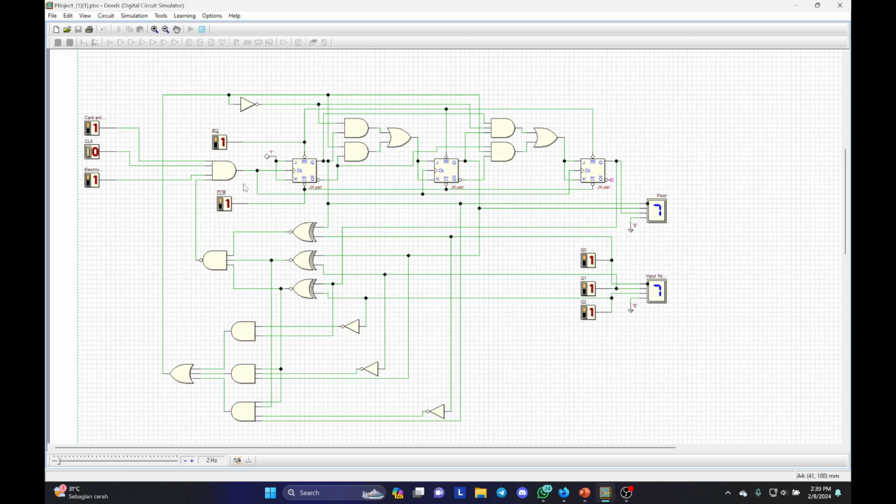Okay, for the last example, maybe let's go to the ground floor, from the seventh floor to the ground floor. Okay, because section A is greater than section B, the button pressed inside the elevator, the comparator in section C will output 1, indicating the lift to go down. Let's push the button.